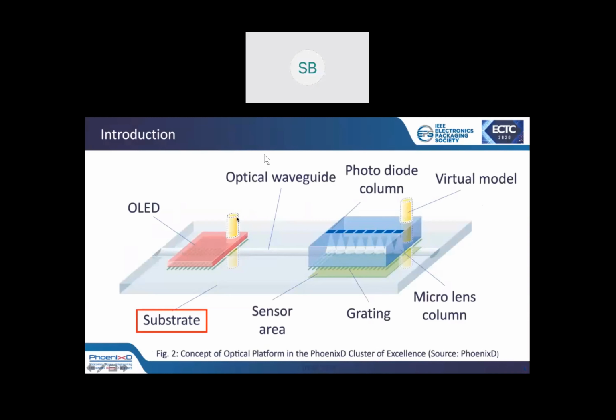In the center picture, you can see the master tool of the injection mold device at the institute. We have in the center of the injection mold a core, and on this core there is an injection mold inlay. This mold inlay is fabricated in-house at the institute using common lithography and electroplating processes. We use steel as a substrate.